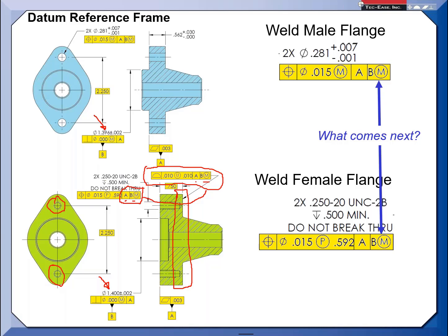And that means one gauge will inspect both feature controls? Correct. In this case, they'll have to inspect the part and qualify both tapped holes and that planar surface at one time, simultaneously. At one time, but that doesn't mean it has to be one gauge. It could be two hard gauges or two gauges. Not necessarily one gauge, right?